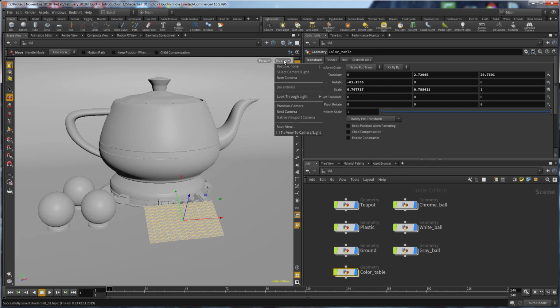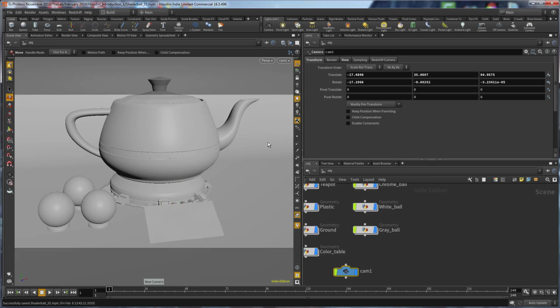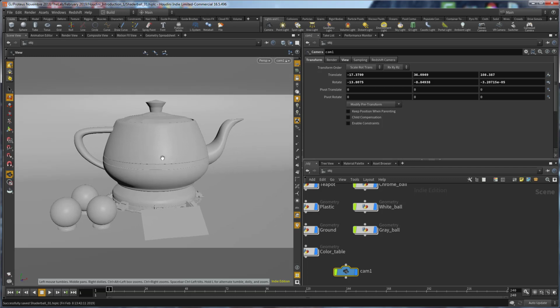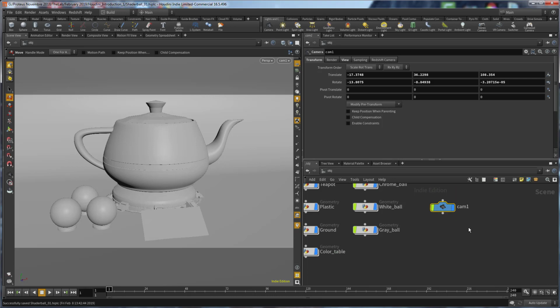We have no camera. You see that there we have no cam. We can press over new camera. In this way we have this camera. So if we go to move there the actual position of this viewport, we have no changes on the camera. To make changes to the camera, you have to lock. So this is locked over camera 01, and this way we are changing the camera. Then if you like to make changes just to the viewport, you have to unlock. Okay, nice.